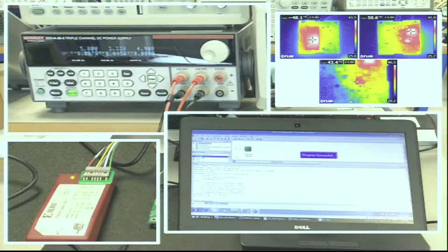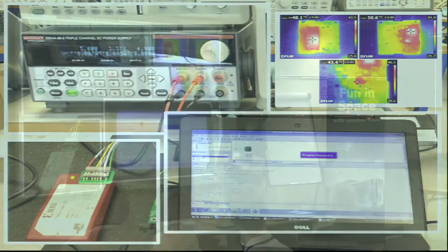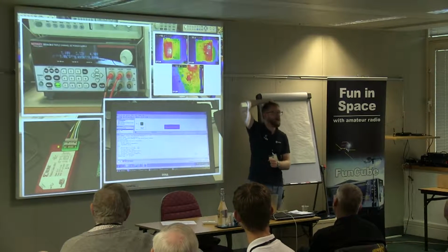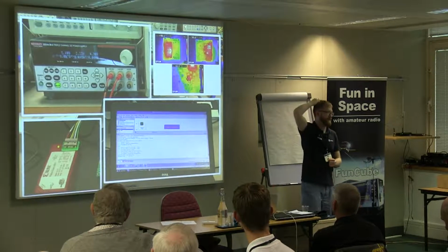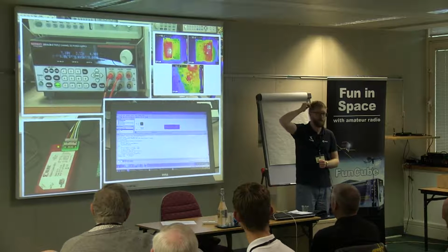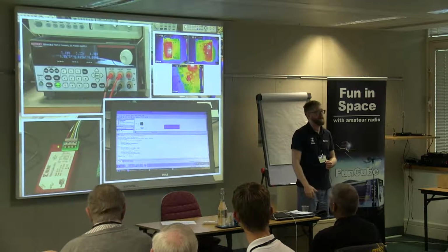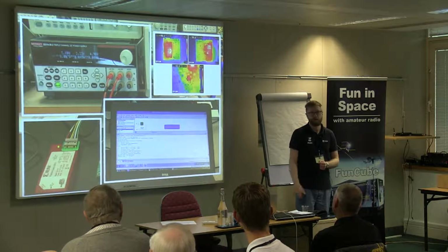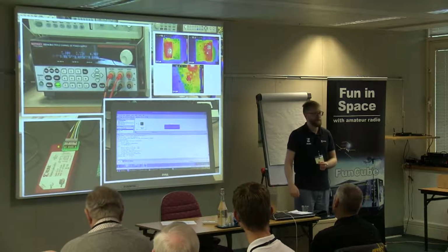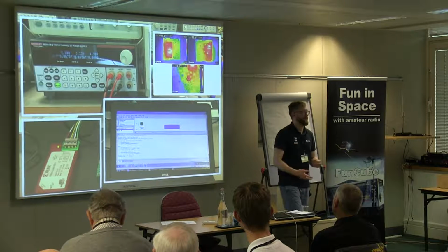Things get hot though. There is one issue that we need to resolve where we're hitting 50 degrees C in air when these things are running, so we are running these quite warm. What we need to do is put a copper strap heatsink, like we've had to do on a lot of our other missions for hot devices. But again, things that you can go through and do.